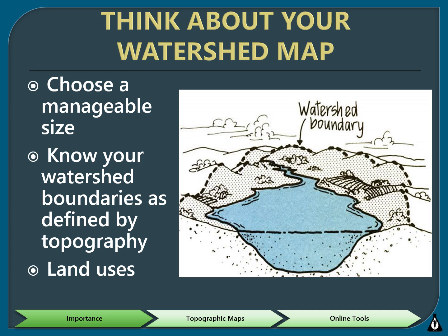You're going to want to select a manageable size. If your watershed's too big, sometimes that can get hard to deal with, so you might want to select a sub-watershed within that one. And again, our goal is to show those boundaries that are defined by topographic lines within the watershed, as well as the land use that's in the watershed, so that you can know where you want to sample, identify those sources of pollution, and again, make informed decisions in your community.